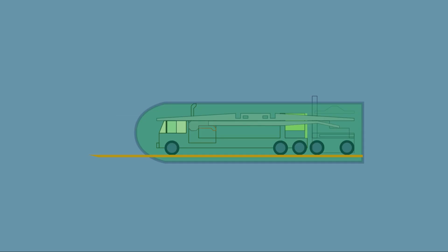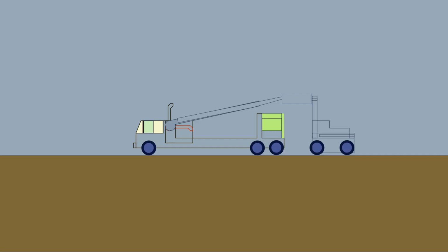The other piece of equipment that is needed is something to pick up and manipulate the 40-foot cargo containers. One option is to have a 40-foot rack that fits on top of the containers and picks them up. That rack could be mounted on top of the vehicle to which it would be attached inside the 40-foot tube. You would also need a forklift. The forklift and the vehicle with the 40-foot container would come out. The forklift picks that 40-foot long rack up off the top of the vehicle. The vehicle comes around, makes a 90-degree turn, make all the attachments, and now you have something that can lift and move the 40-foot containers. And once again, it is a lot easier just to fly it in on a C-17.